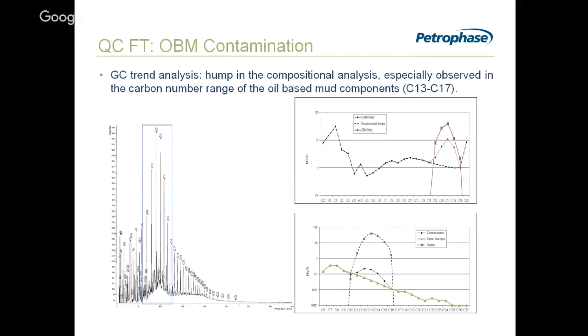If they are oil-based mud contaminated, if you look at the trace on the left, here's an example of an oil-based mud contaminated sample. So we have the background trend of hydrocarbons, and then we have this big peak. This is a diesel type based oil that's been contaminated. So we have this very exaggerated peak around C11, C12, and C13. And there are ways that we can tackle this to try and eliminate it in the composition. Of course, we can't physically decontaminate the sample. We can only measure what we've taken. But if we take measurements of the sample, model that, we can then change the composition and make predictions of what the properties would be without the oil. And if the amount of contamination is small, this can be quite successful.